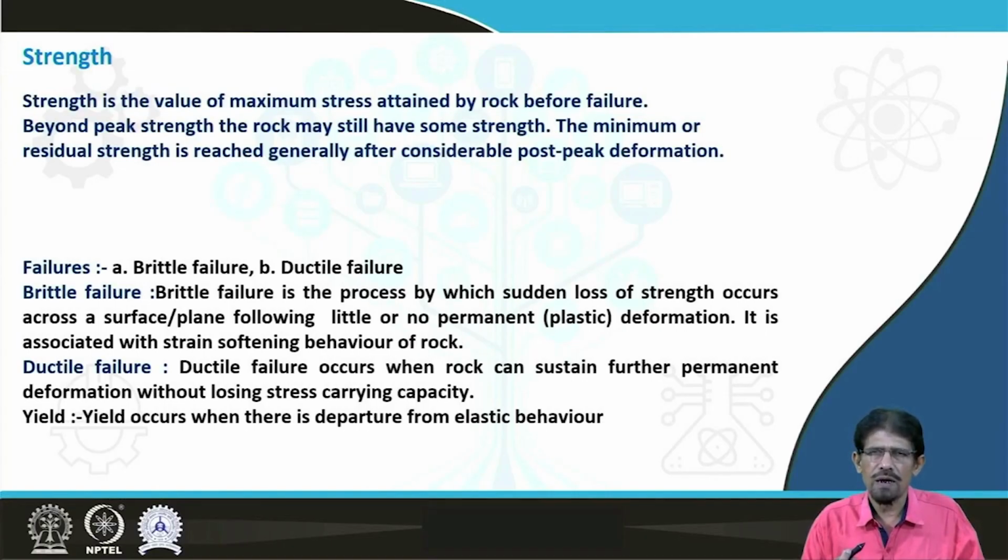The rock in this zone after peak is useful in studying the different modes of failure for proper planning and design of support systems in highly fractured or highly deformed rock. Therefore, the post-failure characteristics in view of stress strain behavior are also very important.